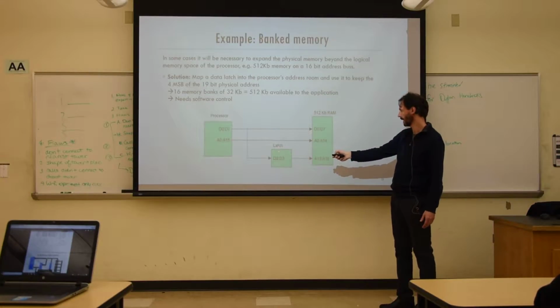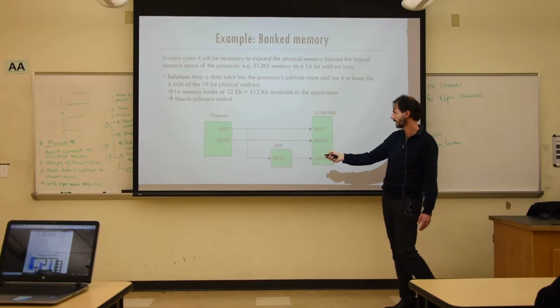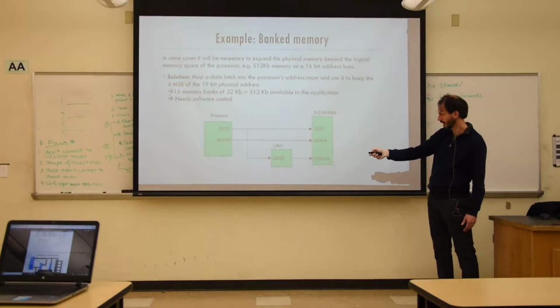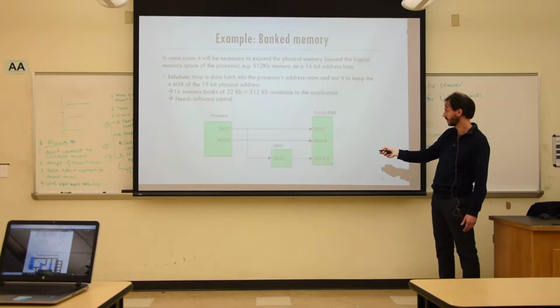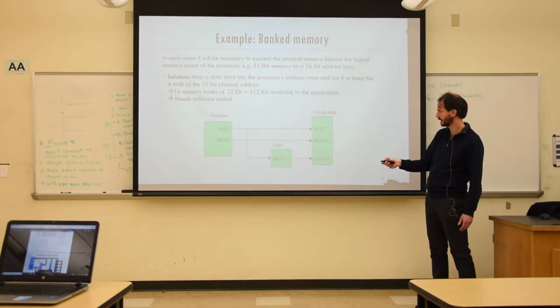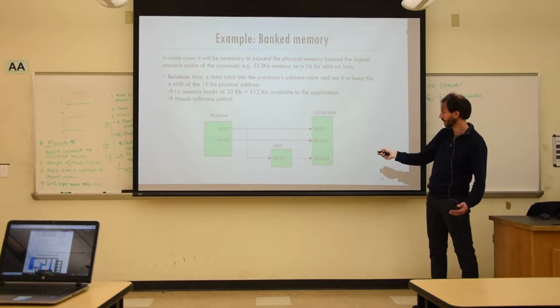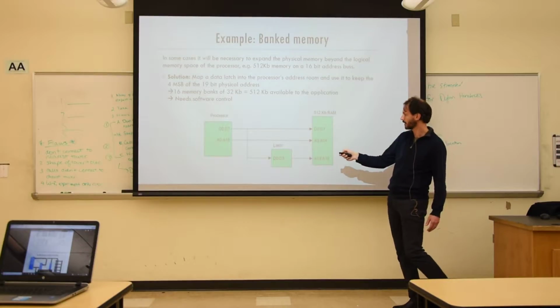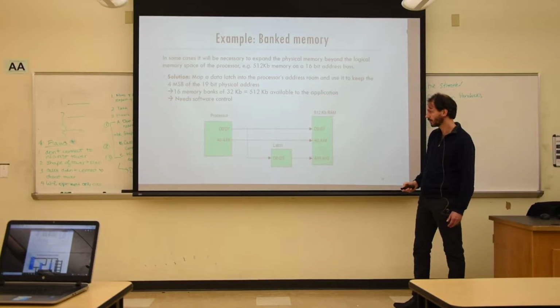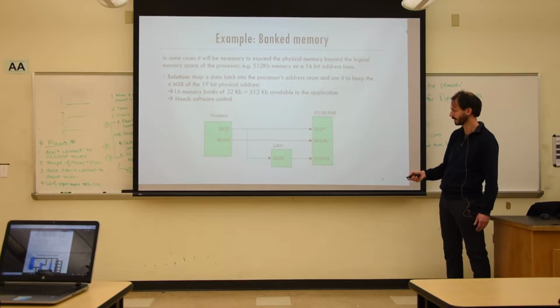So we need to just use a latch again, meaning that we are going to use those 16 address lines to be transmitting, say, A0 up to A14 in this particular case, and you have another 4 bits coming from this latch. You use those address lines directly to feed into your RAM for the first 15 address bits, but the last 4 are given over your data lines. So you use those data lines to sometimes transmit actual data, or say A15 to A18. It's kind of a multiplexing in a different way.